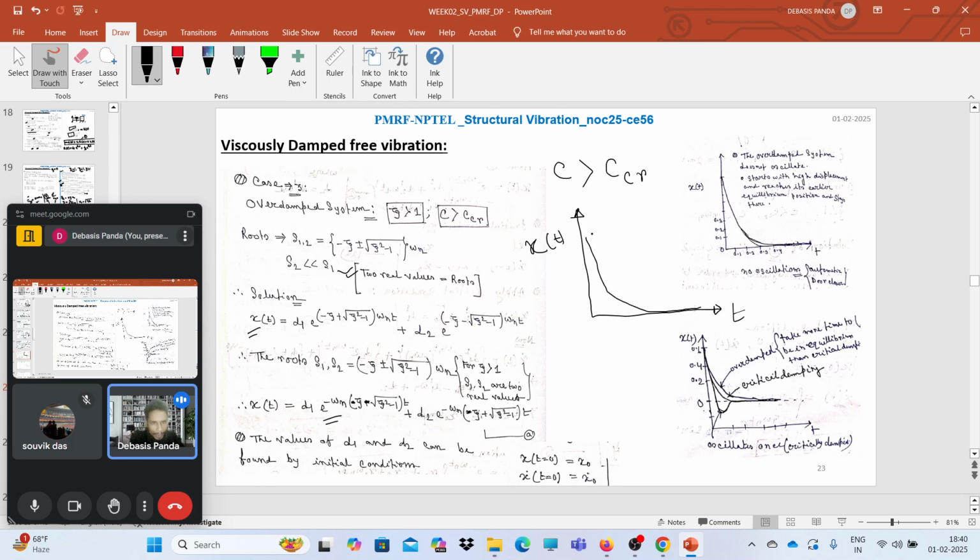And if we plot the overdamped system, the curve will look like this. It will also reach the equilibrium position, but a little slower. Like we have the automatic door closer. We open up the door and leave it. It will slowly go to its equilibrium position. But if we design that door with a critically damped system, what will happen? As long as we just leave the door, it will shut the door, right? So now for this system, we will use the overdamped case.